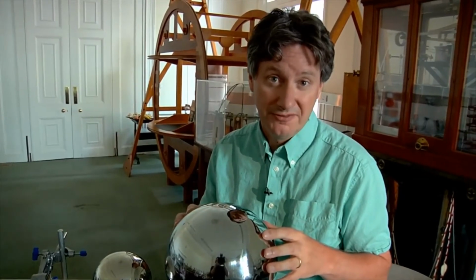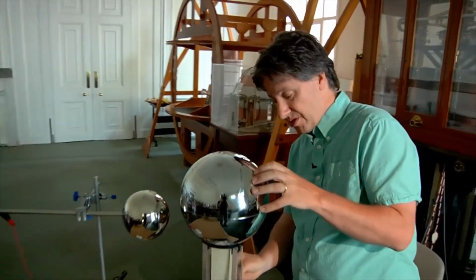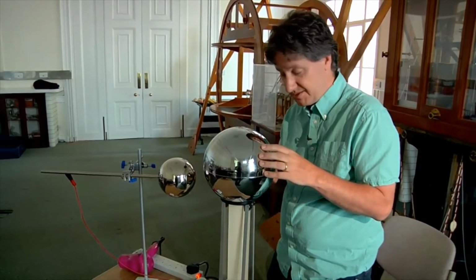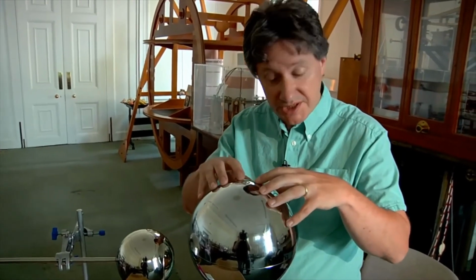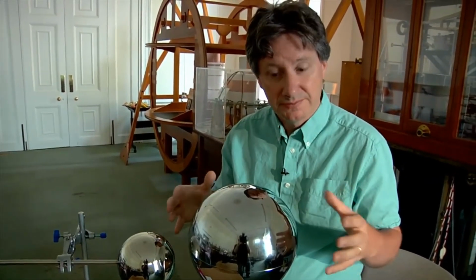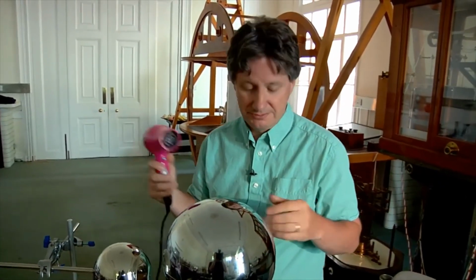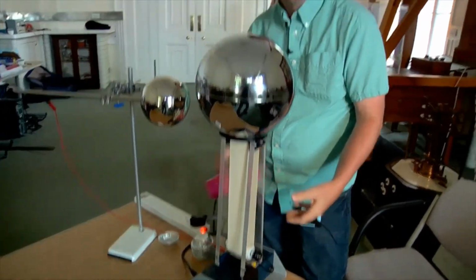When Van de Graaff generators come out of storage, they frequently don't work very well at first, and the usual culprit for this is moisture. Moisture on the rubber belt provides conducting paths by which electrons can work their way back down to the base. Also, moisture in the air provides conducting paths through which electrons on the dome can leak away. So the cure for both of these is a hairdryer. Running a hairdryer over the belt of the Van de Graaff while it's working for about 5 minutes should cure both of those problems.